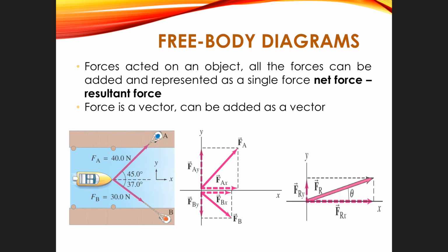Okay, so this is what I mentioned before, the free body diagram, which means that you need to separate that into components, which are Fx and Fy. Okay, because force is a vector. So for you to solve this kind of question, definitely you need to separate that into components and find the resultant force. If the question asks you to find the resultant acceleration, just find the resultant force, which is the magnitude, square root of Fx squared plus Fy squared. Okay, and then if the question asks for the resultant acceleration, just use the value of the resultant force equals ma. Then you are going to get the resultant acceleration. Okay, right, so basically very easy.